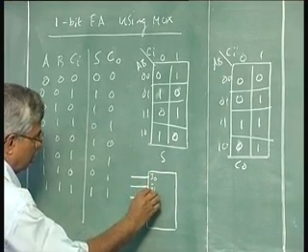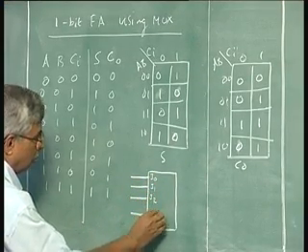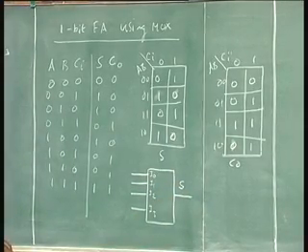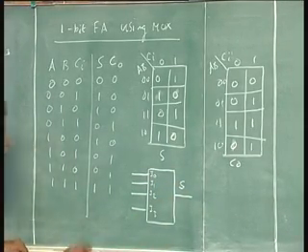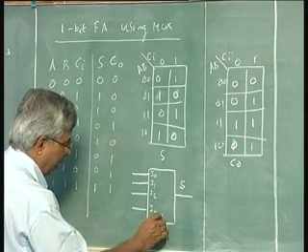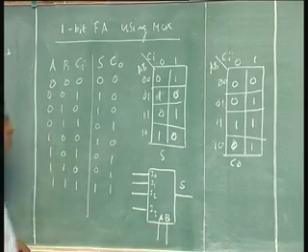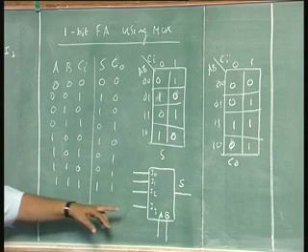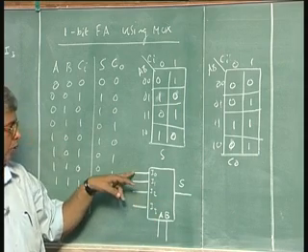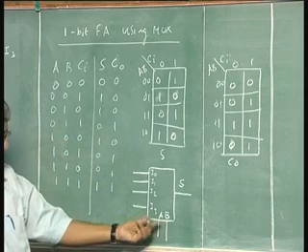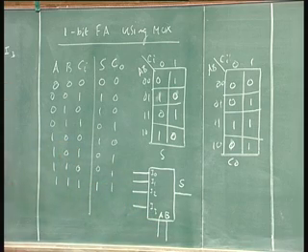I0, I1, I2, I3, and I am going to get a sum out of this multiplexer, and the 2 selectors I am going to use my 2 bits A and B. Now, when AB is 0, 0, you know that output S is equal to I0, is that right? We know that from this equation